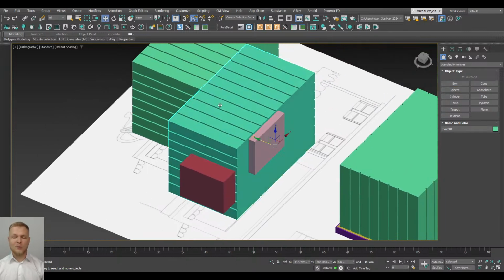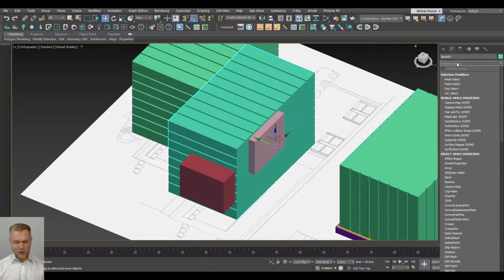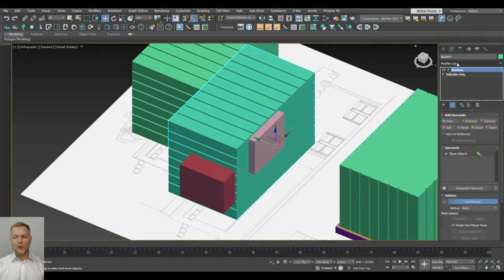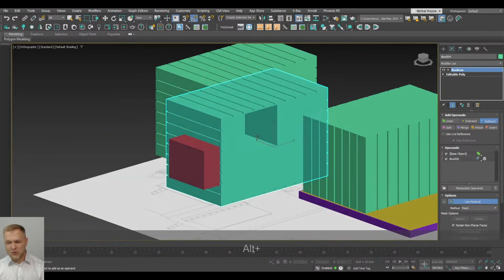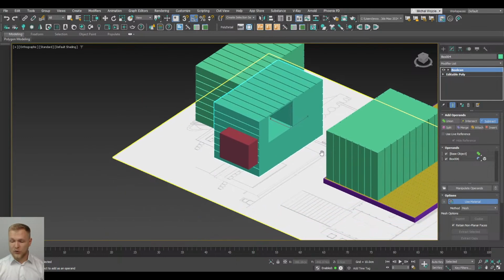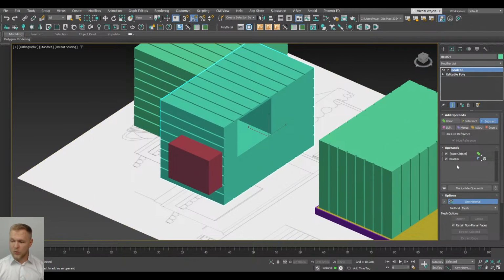So now we're going to select this object and apply a very specific modifier, which is Boolean. Boolean is one of my favorite modifiers right now in newer 3ds Max. We go for that and we are going to be able to subtract our objects one by one. Okay, but the subtraction also creates this, let's say, problem. First of all, the box wasn't in the right place, which is a problem on its own, but also we're running into an issue where it creates this loop around it.